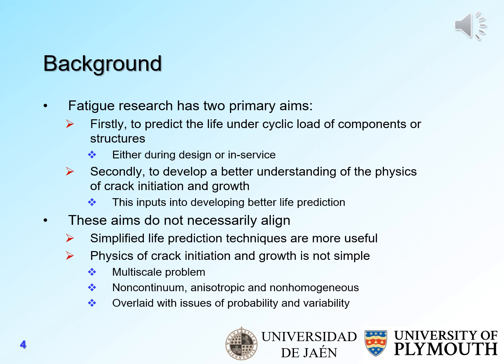Those aims do not necessarily align, because simplified life prediction techniques are more useful, whereas the physics of crack initiation and growth is not so simple. It's a multi-scale problem, it's non-continuum, anisotropic, non-homogeneous, and overlaid with issues of probability and variability. And of course, all of those things are not really what industrialists want to take into account in a simplified life prediction technique.